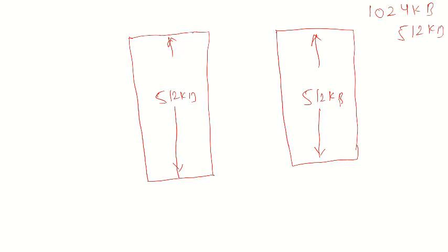So actually, okay. One another thing is, we have divided the whole memory into two banks, and each location of the memory contains 8 bits. It means at a time यहाँ पे क्या होगा 8 bit data store होगा. But for some applications we want 16 bit data at a time. So how can it be done? So let's discuss. Suppose we have divided this whole memory into two banks.